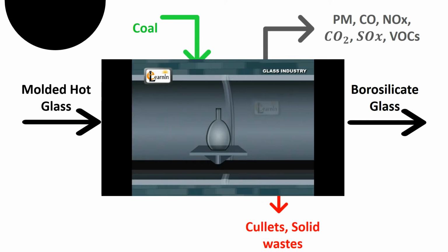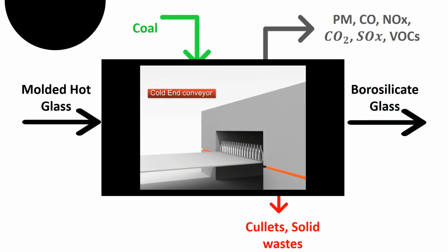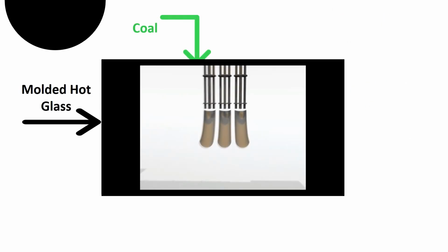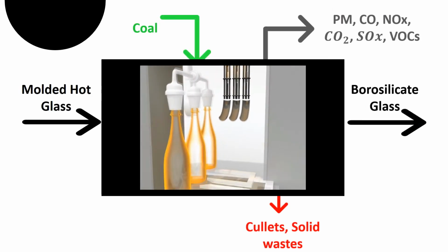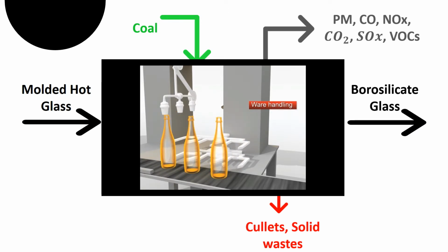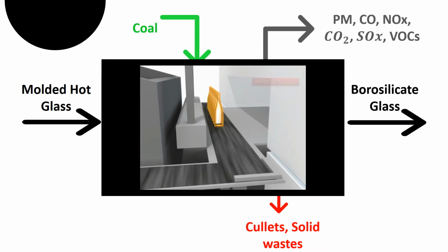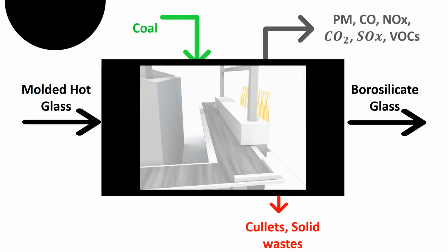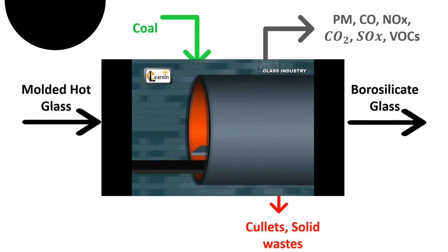The second stage is recrystallization, where new strain-free grains nucleate and grow to replace those deformed by internal stresses. If annealing is allowed to continue once recrystallization has completed, then grain growth, or the third stage, occurs. In grain growth, the microstructure starts to coarsen and may cause the metal to lose a substantial part of its original strength. This can, however, be regained with hardening.